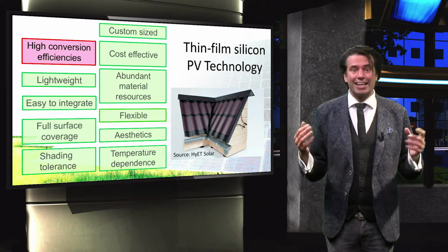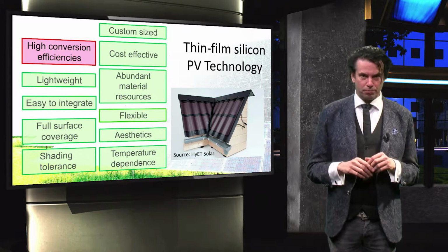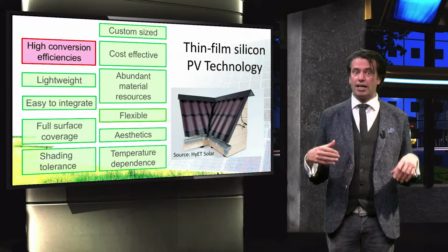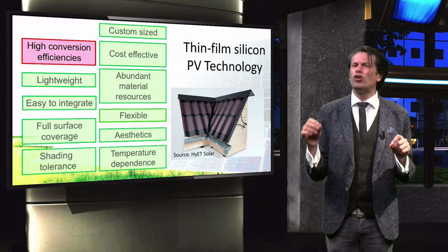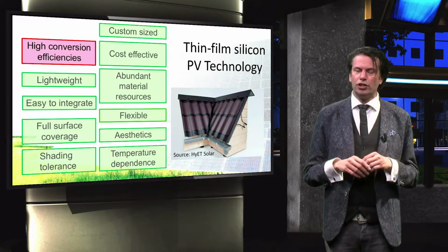This allows high-tech integration of modules in building elements like in this picture. This technology allows easily customized module shapes and highly aesthetical applications. In addition, the multi-junction modules have a lower temperature dependence, which makes the performance less sensitive to temperature.